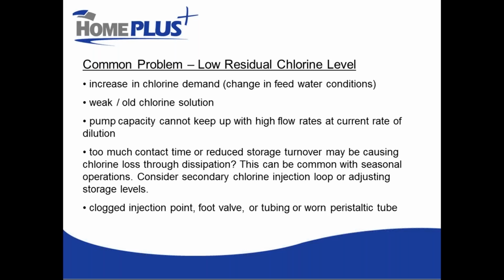Essentially, that means your pump has fallen behind where it needs to be to keep up with your flow rate. The pump will continue trying to pump to catch up after the water shuts off. It's a really strong sign that your pump capacity is not keeping up. If that's the case, your dilution rate might be too strong and you'd be better to go back to a slightly stronger solution with less dilution.